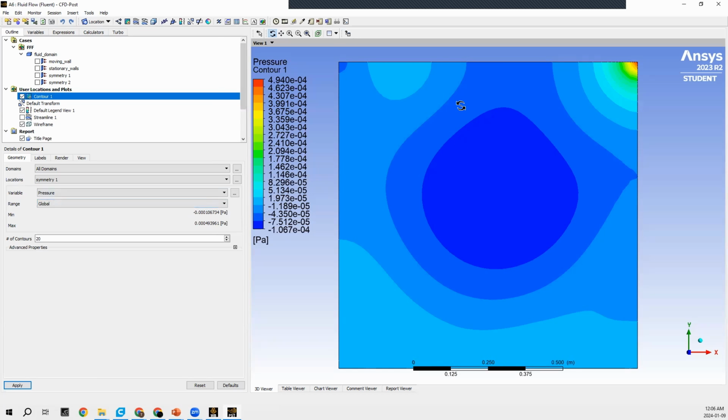And as you can see, the results that we've obtained are fairly good due to the movement of the upper wall in the X direction with some velocity and the no slip boundary condition. This is causing the flow to circulate to this area, causing an area of higher pressure. And as a result, the only way that this flow can escape is downwards. So this is what ends up causing the swirling motion that we saw within the streamlines.